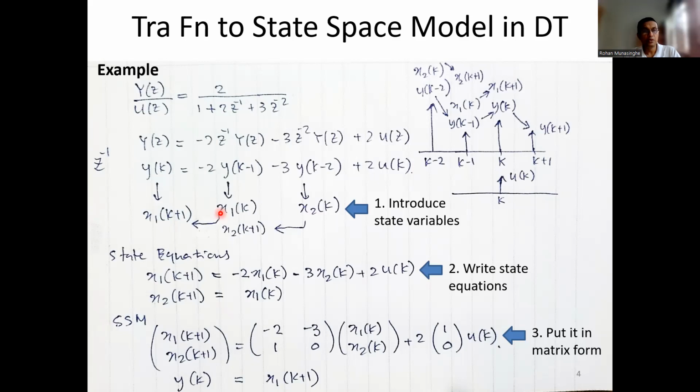Okay. So this is a little technique that we do to bring all the past information into present context, past information into present time. And if your denominator is a second order, you assign two state variables, x2 and x1. And when you do that, you have the dynamic equation, the difference equation over here with yk on the left hand side, and this one is